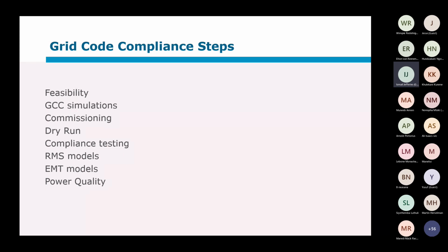Okay, we know the newer ring main units do have the ability to add SCADA facilities, and that's also another debate moving forward. Will we now allow that and not insist on a protected substation with proper control switchgear that can facilitate the SCADA requirements? So yeah, it just becomes obviously a cost issue on the customer side as well, to be able to facilitate these things. Thanks.